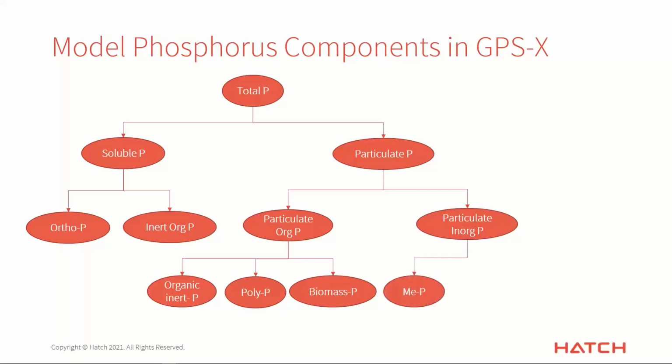And on the inorganic side, we have the various metal phosphates that we would potentially generate if we were doing chemical phosphorus removal. And some of that actually happens even in the biological reactors. You get a little bit of precipitation. But then also, of course, the types of precipitation that you would get with the other inorganic components like calcium and magnesium and potassium and so on, those combining with phosphorus and precipitating out, such as struvite, which is the most common one. And then actually in our model, as I'll show you here in a few moments, there are actually quite a few precipitates that will remove phosphorus from the system.